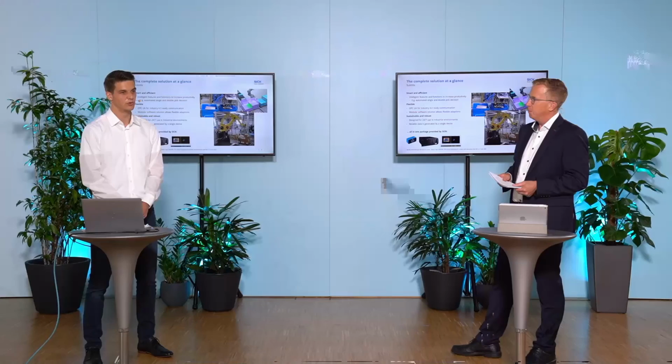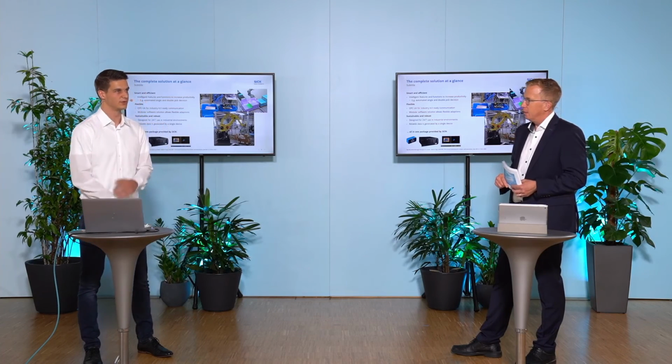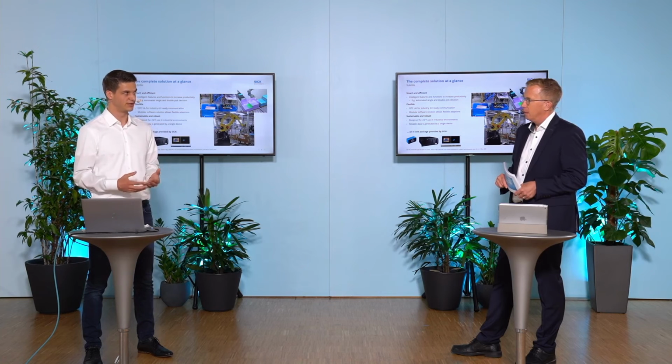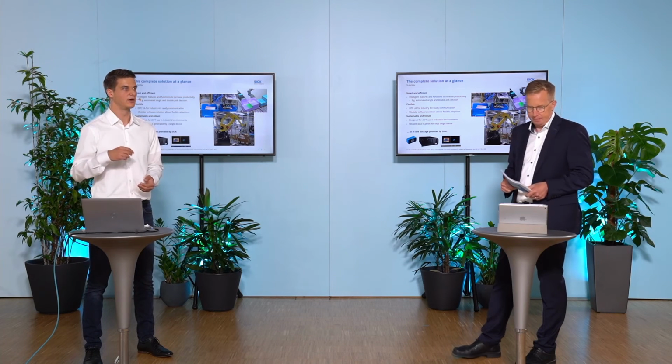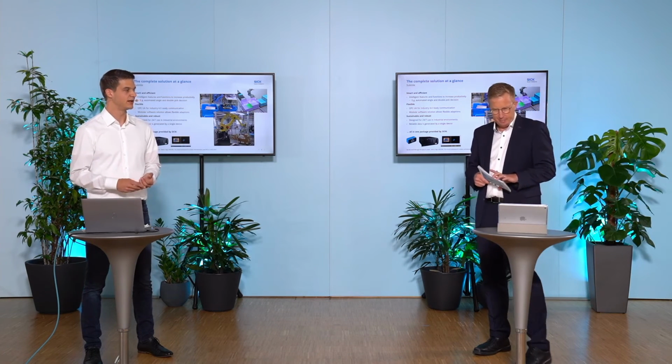So this must help as well with the speed of picking, right? Yeah. In this case, we are flexible. We can work with the entire stream of 3D data incoming in the controller, but also, in order to make it more efficient, just on a triggered event. We can send a trigger to the camera, and the camera only takes a snapshot when it's needed. Right. So the control unit and the software just need to handle the one image, and this one image contains the complete 3D information. Yeah, very good. Thank you.